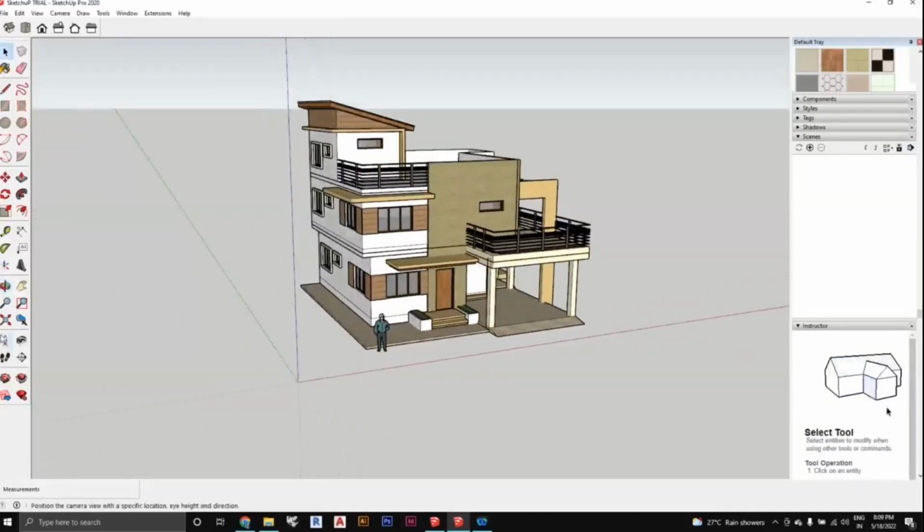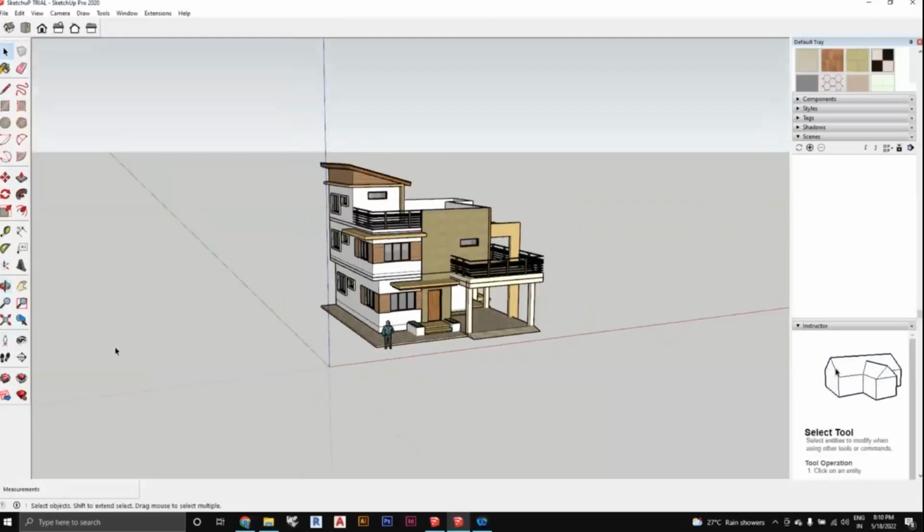So I'll talk about the animation tools that are in the toolbox which we missed in this toolbar. These tools are used for animation purposes, for creating walkthroughs. Okay, the first thing is Position Camera. Position Camera is, if you are a human being standing at a position and looking at the building, what your exact view of the building will be is shown when you use this tool.